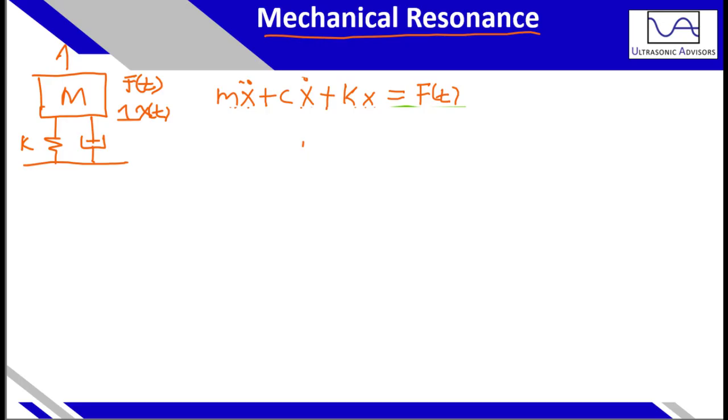And that's going to equal your forcing function with time, and if we generally describe a forcing function, it's going to have an amplitude, and it's going to be in phase with itself. So we won't write any phase out here. In general, it might have a phase, but if you reference your outputs from the input, which is the force, then you don't have to describe that with any phase value.